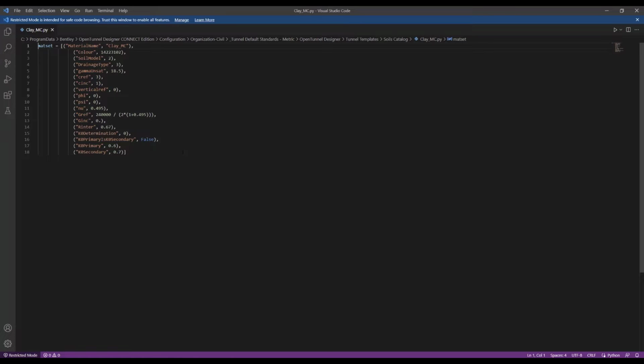during the calculations. This is the current workflow that we are using for PLAXIS version 21, but starting with version 22, we'll have access directly to the PLAXIS material database, so there will be no need for editing or adding new materials using Python scripts.